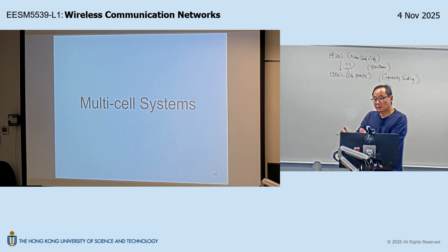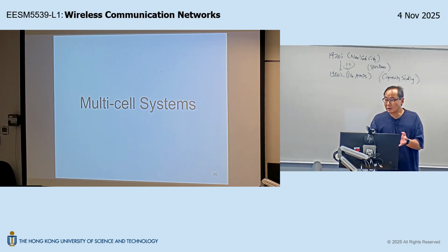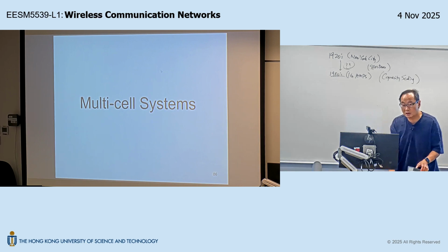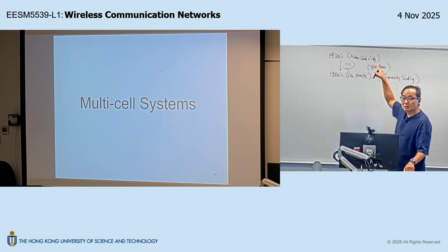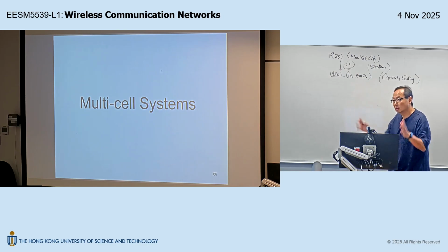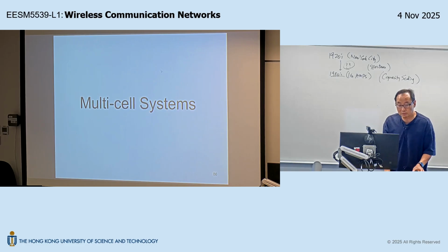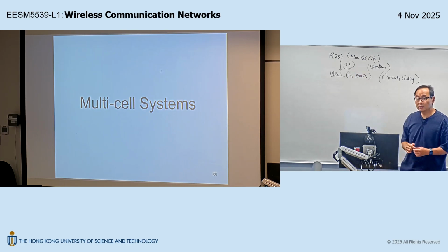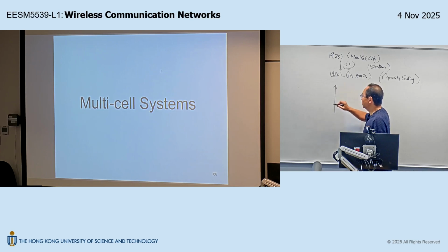Because as I said, good spectrum is very limited, right? Even today, you won't be able to easily expand the bandwidth by 10 times, not to mention thousands, tens of thousands of times. So to bridge this capacity gap by just naively increasing the spectrum is just not the solution, because there won't be that amount of radio spectrum available, right? Because we are talking about a huge amount of scaling. So that is the missing piece. At the end, what's the solution? So how did people figure out the solution? The solution is very nice. It's called cellular architecture.